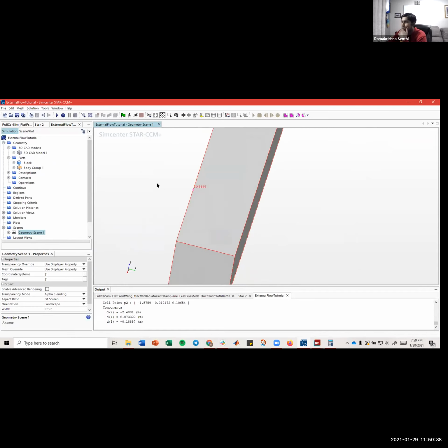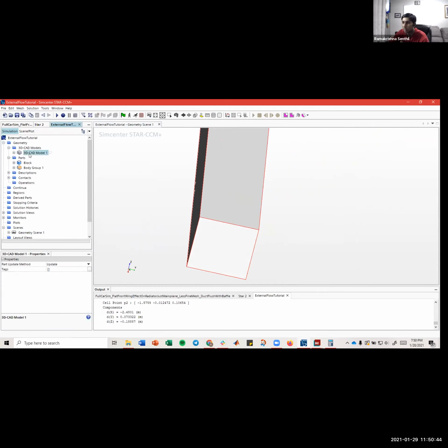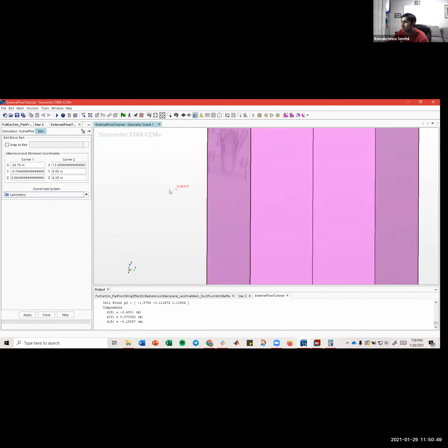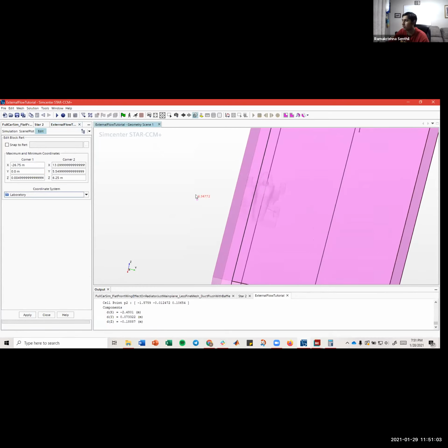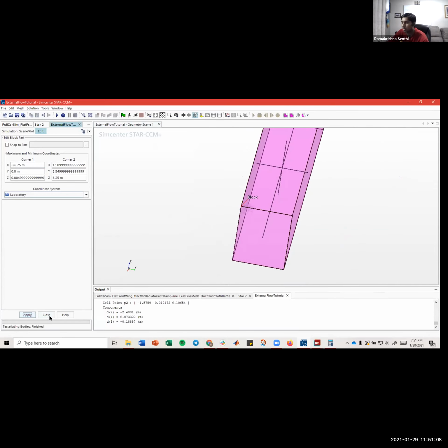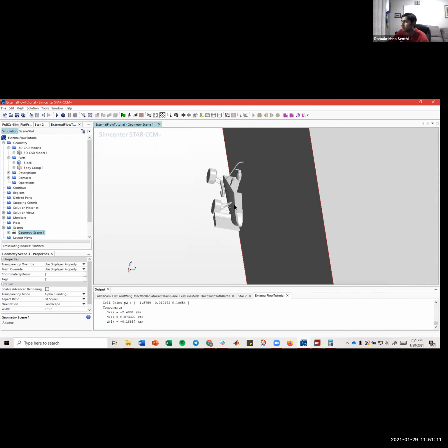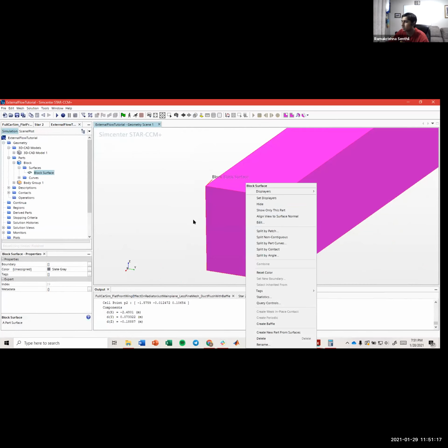One other thing is that since we are only going to be modeling half of the car, that block needs to be edited so that the right side of the car right here is at the 0 point halfway. So we could just change this negative 0.7 value to just 0, and it should be exactly halfway. And just click apply, close, and then there we go. So yeah, this is what will be modeled.